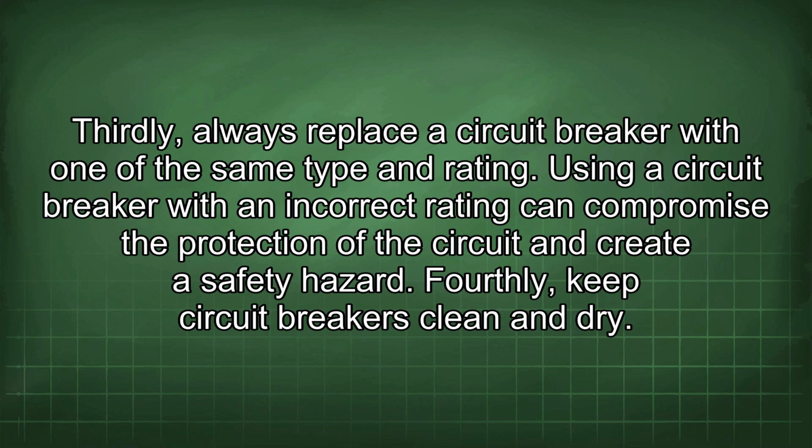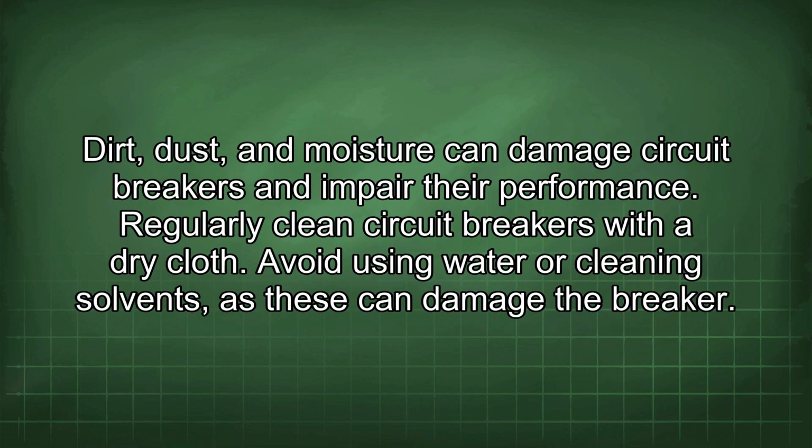Fourthly, keep circuit breakers clean and dry. Dirt, dust, and moisture can damage circuit breakers and impair their performance. Regularly clean circuit breakers with a dry cloth. Avoid using water or cleaning solvents, as these can damage the breaker.